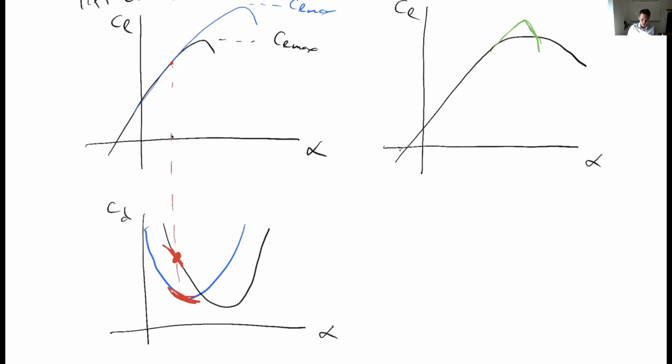We haven't gotten to that, but you do know your wing lift coefficient. Your airfoil lift coefficients are going to be a little different. They'll vary through the wing, but for now, on average, your average airfoil lift coefficient is going to be the same as your wing lift coefficient. So I would use that for now, again, as an average. Okay, so those are just a few properties that you're going to want to look at.